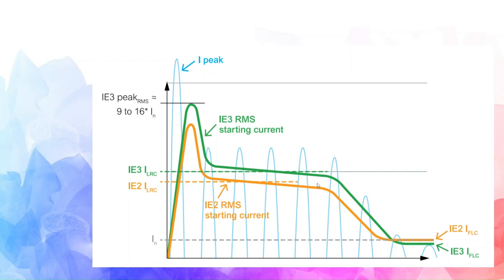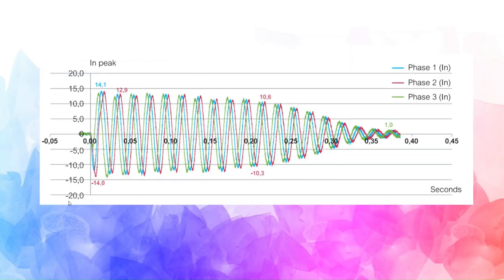Let me show you something that probably you have not seen. Have you seen this curve? When I saw this curve for the first time, when I was in the fourth year of my engineering doing a project, I was surprised. What is this? So this is also the starting current, time current characteristics of an induction motor. But this is not the RMS curve. This is the instantaneous curve. So that's how it goes on ups and downs. So that's the current curve.